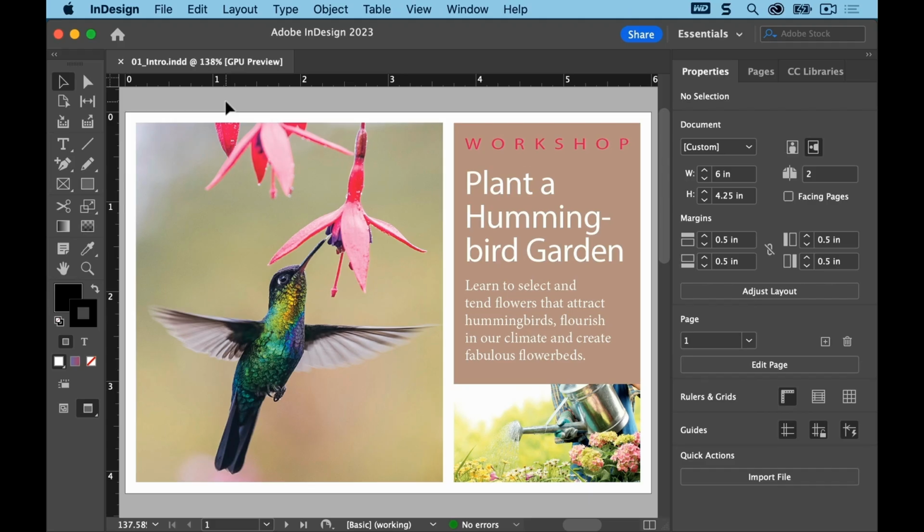The Selection tool lets you move and resize objects, and it lets you select objects for formatting, such as applying a fill color. Here, you will click to select the Selection tool. Later, you will experiment with other methods of selecting tools. Locate the Tools panel at the far left side of the screen. Point at each tool in the Tools panel to see its name. Click the Selection tool at the top of the Tools panel.